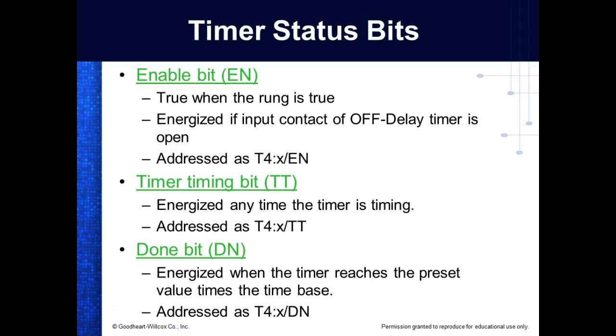The enable bit, they do this the same way. So we have an enable bit that basically we're using at the same time, right? You understand? Then we have a bit in there called timer timing, which does not give us a contact, but it's available to us. So when I start the timing, this guy would become true, and when it stopped timing, it would do what?